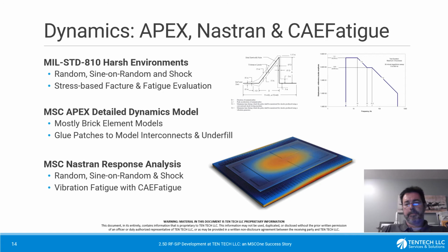And again, for this one, we built some very detailed dynamics models in MSC Apex, almost exclusively brick models. It turns out that the geometry of those things is very conducive to using brick elements, and we model every solder ball, every solder, every landing area, all this to look at all the possibilities of fracture and fatigue failure.